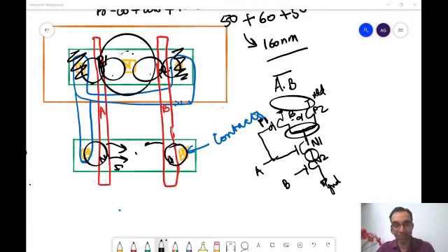Do we really need such wide transistors? Sir, actually we didn't know how to cut the PMOS and NMOS into fingers. So I literally placed one below the other vertically by generating it, and that's how it happened. Sir, there is a 20 femto load on the inverter. Okay, for a 20 femto load you have to make it 7 micron. Sir, and they were asking for 20 picoseconds. That was not possible using NSVTLP, or a bit hard to achieve, but it was happening in NLVTLP.